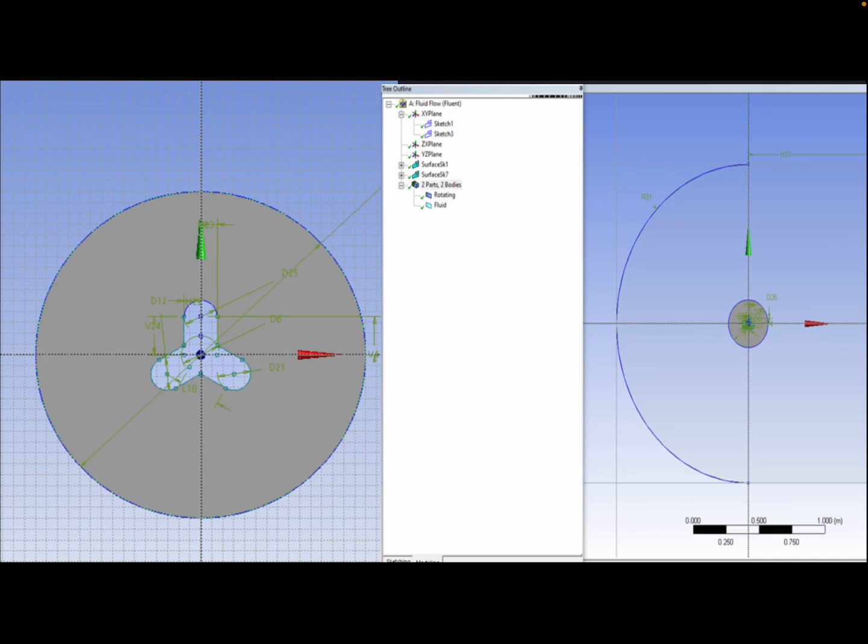This arc here will have a 1 meter radius. The horizontal length of the rectangle, which you can't really see in the slide, but there's a rectangle connected to this arc going to the right, will have a 1 meter length or width, I guess, and then a 2 meter height to cover the whole diameter of the circle. And then to finish it off, you'll want to draw a circle over the same circle that you drew for your rotating circle for the fidget spinner. And then you'll do a concept and surface by sketches to make that surface there.